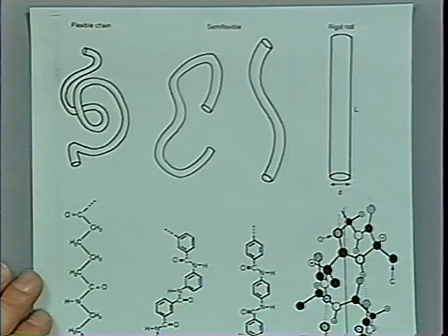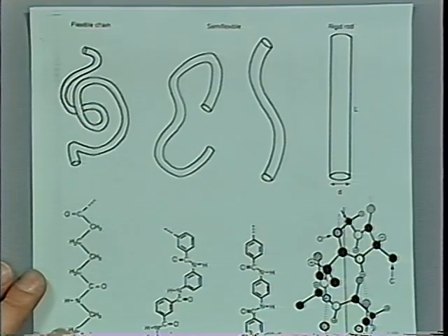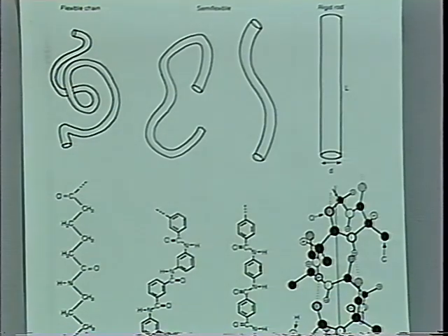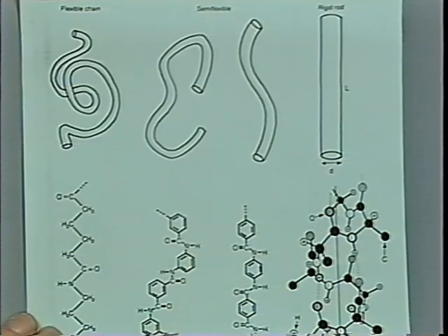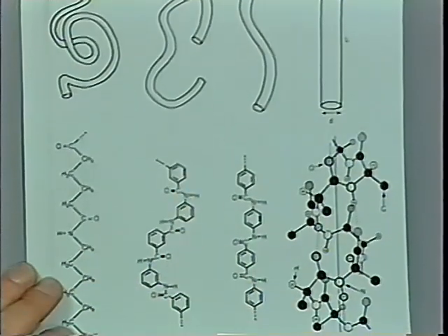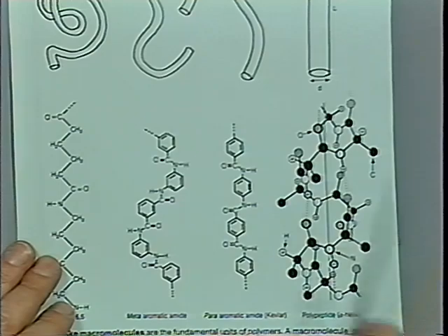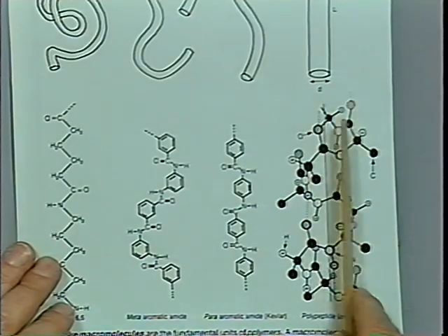The order comes from the molecular structure, which is changed systematically by the chemist. Here is an example of a very flexible chain, like a polyethylene chain. But if you put in some aromatic groups, or if you have this CO double bond group, NH groups, the amine unit, then you obtain some molecular stiffness. And if you have some even further elaborate molecular structure, then the molecule cannot bend at all. It will be completely stiff.